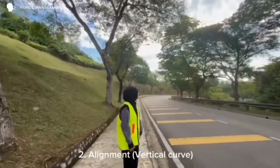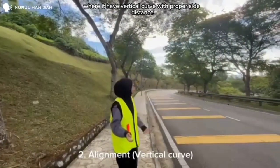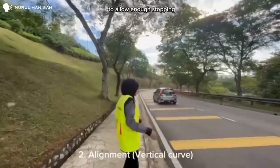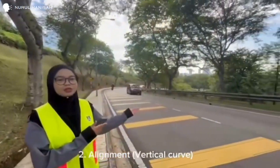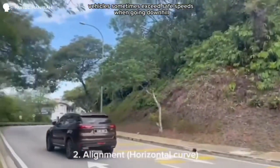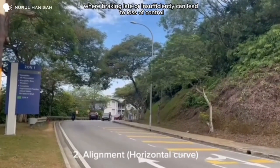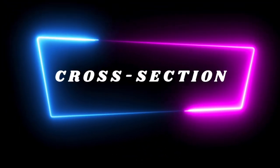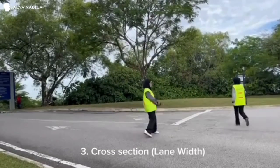Alignment. Next is alignment. This junction has a good feature where it has a vertical curve with proper sight distance to allow enough stopping sight distance for drivers to see another vehicle. Vehicles sometimes exceed safe speeds when going downhill through the horizontal curve, where braking that is insufficient can lead to loss of control. Cross section. Next, I will explain the principle of design for safety, focusing on cross-section elements.